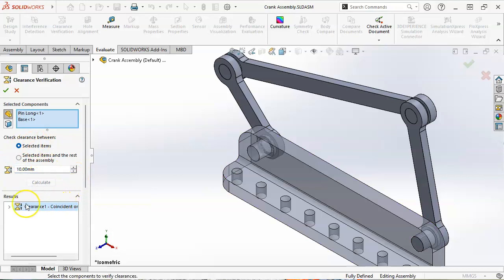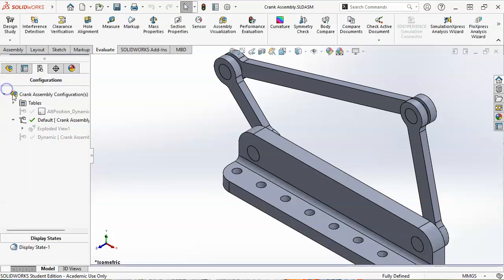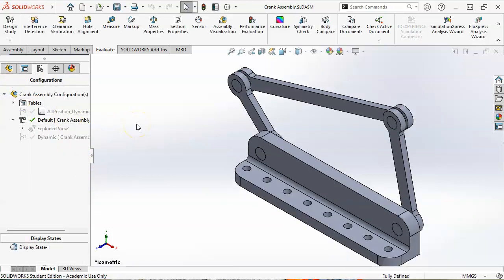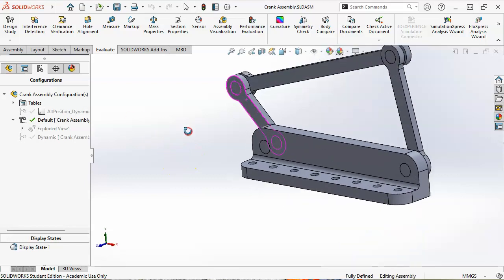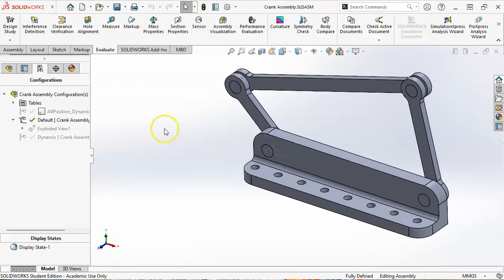Let's go ahead and calculate clearance. 1 is coincident or interfering, so that tells me that I'm at that line to line. I have not built in any tolerances or gap tolerances. On the one side, that has the benefit that if I go in and start to do a simulation that places loads on these, it doesn't have to calculate across that gap. So it's still a manipulating, juggling numbers thing to make all of this work.